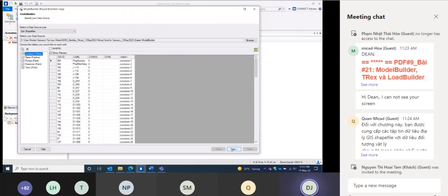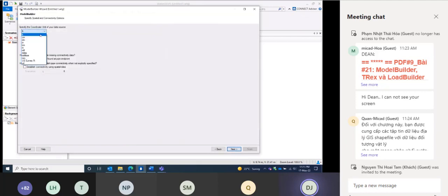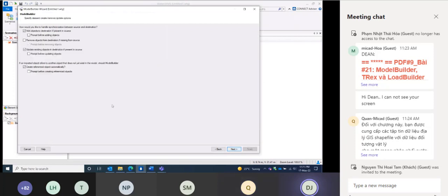Okay, go ahead and click Next. Of course, we need to select meters. I'm going to untick Create Nodes if none found at endpoint. Then Next. This one here is fine with the defaults; we'll come back to that later.